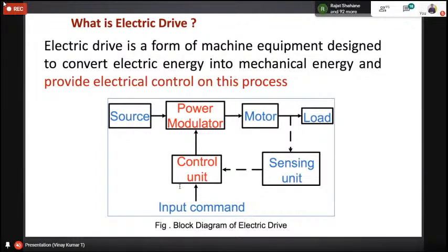As an electrical engineer, your job is the selection of KP and KI values based on the customer requirement or the conditions. You need to maintain error always 0. So if you want to select proper KP and KI values, the first step is you should have the mathematical transfer characteristics of the load, of the motor, of the power electronic module, and of the feedback unit.